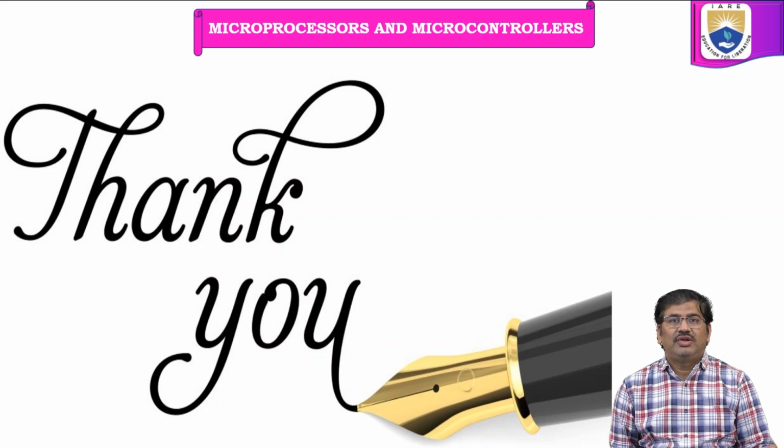Next is LEA, which stands for load effective address. This is used for fetching the offset value of a particular operand in the data segment into the target register. The next instruction is LDS or LES, which is used for loading the data segment and extra segment along with the register specified in the instruction from the memory which you have specified in the instruction.